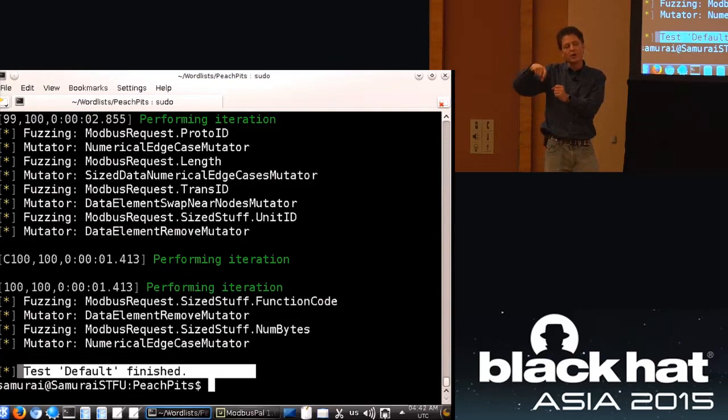And you can create firewall rules saying only allow this IP address from the master server to talk to it. Don't allow anybody else to do it. In fact, on the application-aware one, you can also say that the master server from this IP address is only allowed to send write messages to these 5 addresses. So it's an application-aware firewall rule set. So that's what we can do right now.